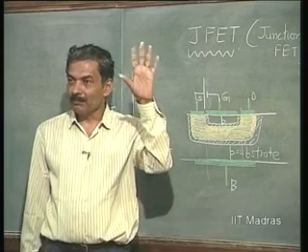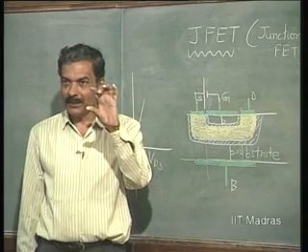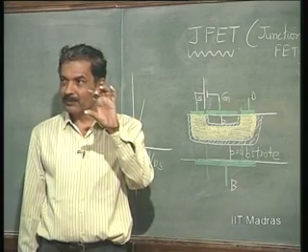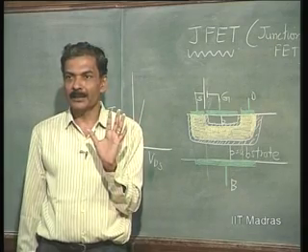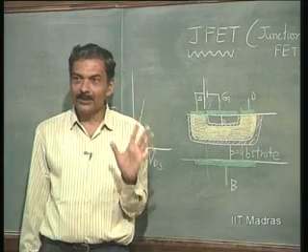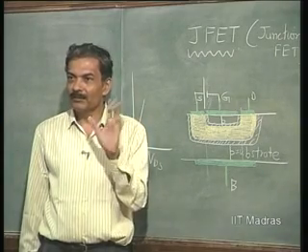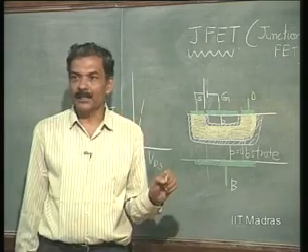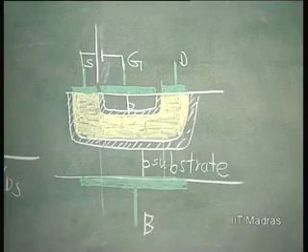There was no problem there. Gate was insulated from the channel by a silicon oxide layer. We could bias it positively or negatively, strictly speaking, right. No current was going to flow. Only thing is, in order to cause MOSFET action, we had to bias it with positive voltage in the case of N channel. So, this is the kind of voltage.